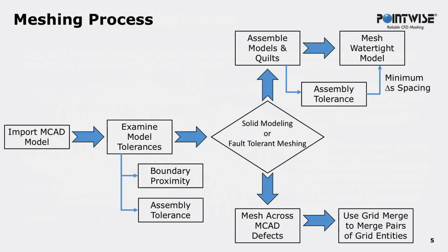So this brings us to a recommended Pointwise meshing workflow for users to follow that should handle most of the cases they encounter. Import your geometry. Use the native CAD file format whenever possible. Pointwise version 18 has some new useful examine metrics that enable users to quickly identify potential problem areas in CAD after importing the model into Pointwise.